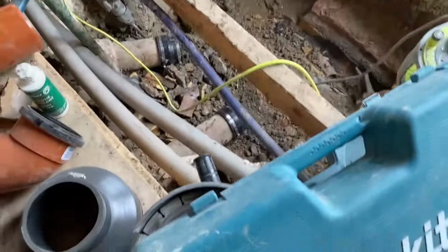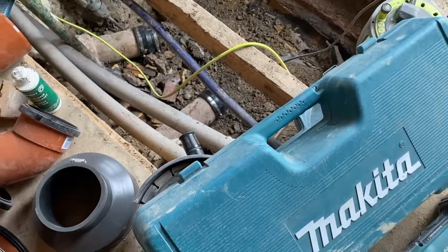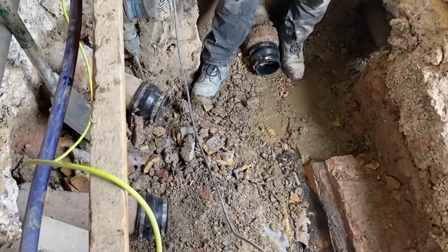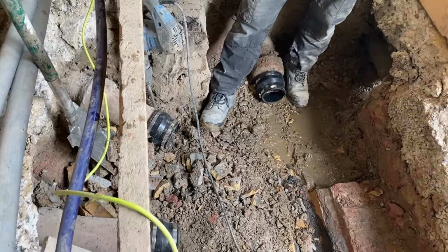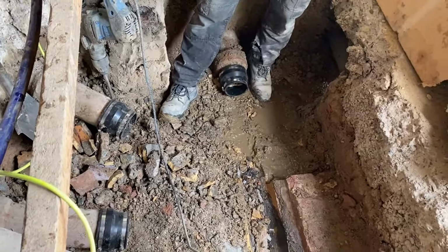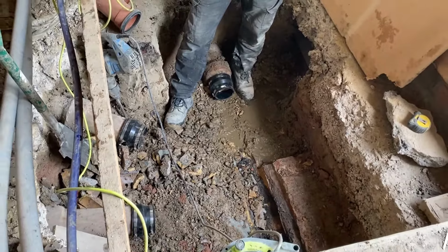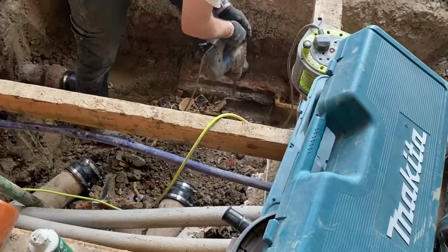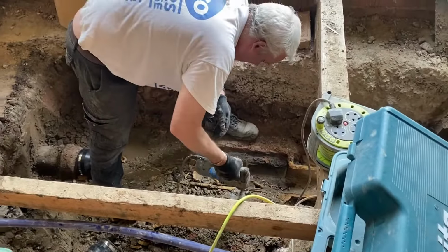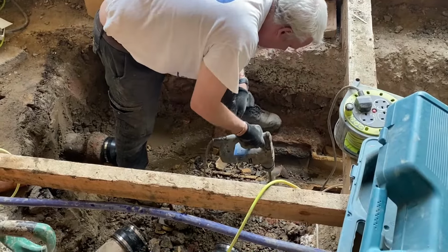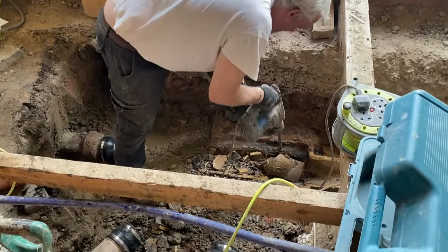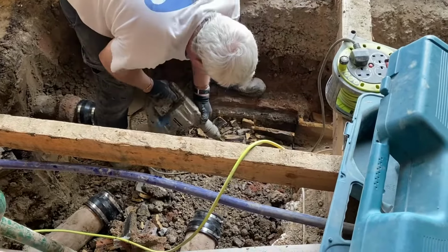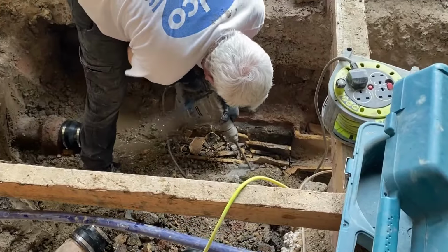Okay, so it's now time to make the connections. Now you can see there are 3 pipes here that we have capped off. So the one between the guy's legs is actually the live sewer pipe. So we've put a plug on that. So that means that anything that's coming live down that pipe will just be sitting in the pipe for the time being, which means we've only got a short period of time to be able to do this work, because otherwise all the sewage will back up for the other people and could cause a major problem. So as soon as you cut the sewer pipe, you've really got to be focused on what you're doing and get the job done quickly and efficiently, because you're stopping the live sewage coming through from the rest of the road.